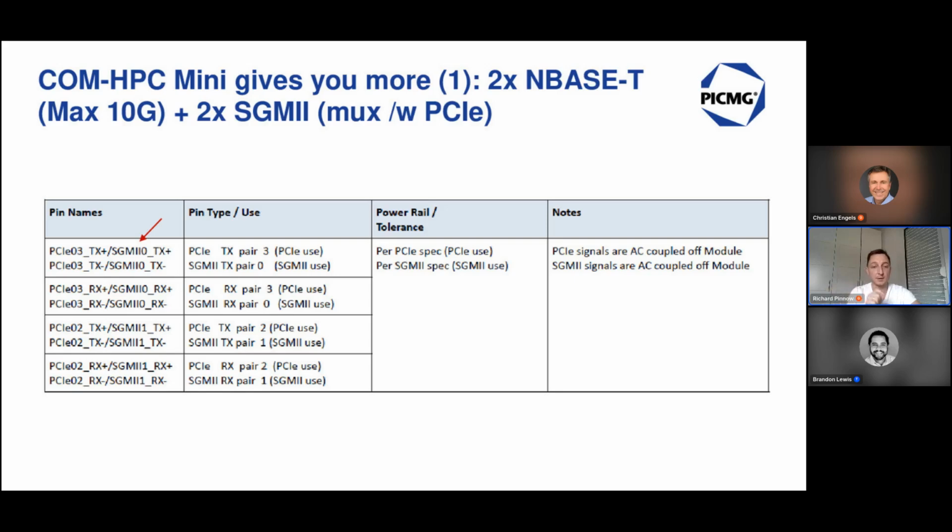Background: the second N-base-T port on the Client was on connector J1, but due to the fact that this simply does not exist, because we only have one board-to-board connector, it has to be relocated to another pinning. The Ethernet magnetics shall be implemented on the carrier board. That's clear. As a general rule, all CPU modules shall have at least one 1G Ethernet port.